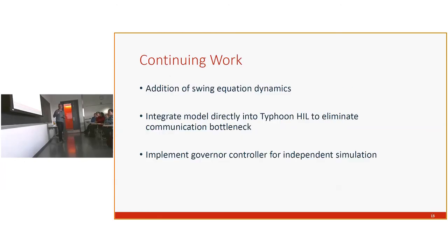So just some continuing work. This is almost done now. Just a few more things to add is adding swing equation dynamics to the model. Now, I said OpenDSS doesn't have dynamics, so what am I talking about? Because we're driving OpenDSS through different software, in this case MATLAB, you can implement these dynamics in MATLAB and then just feed the updated values into OpenDSS, and it will calculate it in steady state in OpenDSS, but you're giving it dynamic values.